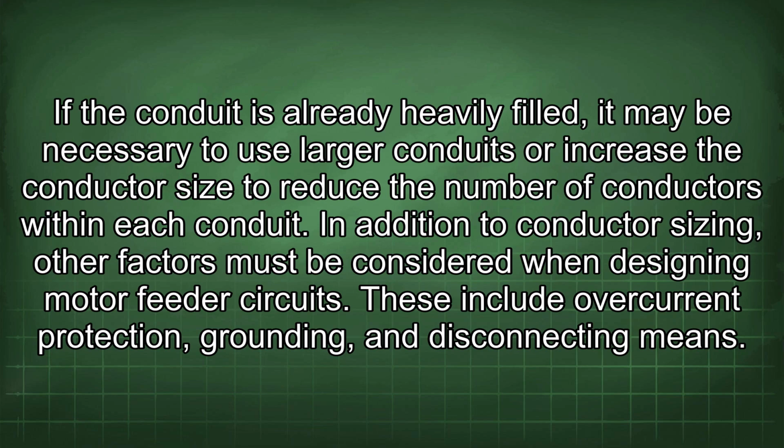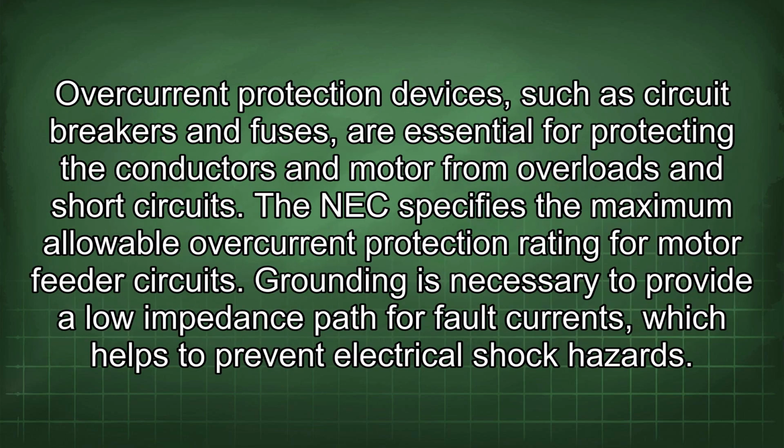In addition to conductor sizing, other factors must be considered when designing motor feeder circuits. These include overcurrent protection, grounding, and disconnecting means. Overcurrent protection devices, such as circuit breakers and fuses, are essential for protecting the conductors and motor from overloads and short circuits. The NEC specifies the maximum allowable overcurrent protection rating for motor feeder circuits.